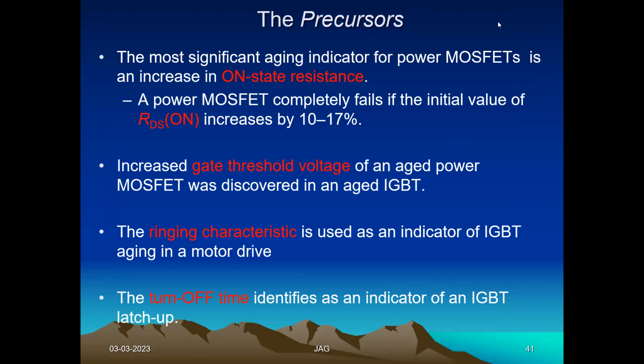Similarly, if you want to identify the failure of a solid state inverter. What is an inverter? The power electronic device which converts DC to AC is an inverter. So how can you identify the failure of a component in the inverter? By monitoring either the output voltage or the output current, you can predict a failure in the inverter.